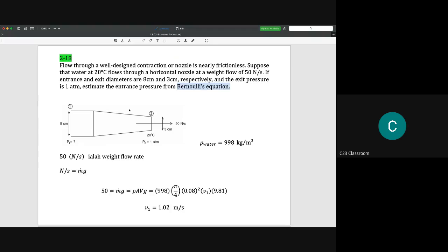Whether the fluid medium here is air or liquid, it might not be compressed yet. If the density changes between inlet and outlet here, you cannot use the Bernoulli equation. You need to use the compressible flow equation.